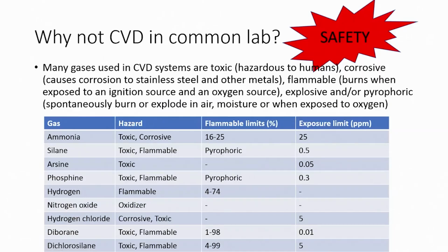So, why is CVD not commonly used in the lab? Except for a few bigger fab labs, CVDs are generally not commonly used, and the reason is the safety factor. Many gases that we use in CVD are toxic, that is, hazardous to humans.